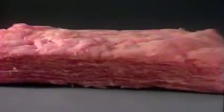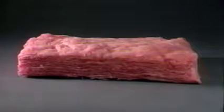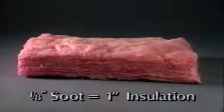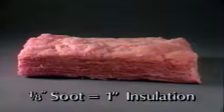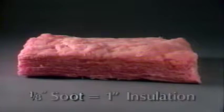Insulation is the last thing you want between the combustion chamber and the heat exchanger. But that's exactly what you get with soot buildup. It's estimated that 1/8 of an inch of soot is equal to 1 inch of fiberglass insulation. This is why heat exchangers should be cleaned annually.